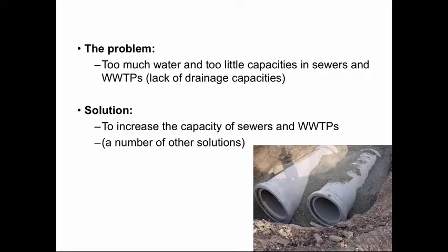So what can we do to solve this? The easiest and simplest thought is, okay, if the sewers are too small, why not build new sewers? But this is not that easy. If you take the Norwegian case, we can't even keep up with the normal rehabilitation needs. The industry here has estimated that we need to renew our wastewater pipes by at least 2% every year. The minimum expected is 1%, but the result is 0.6% per year. So that is just to rehabilitate the existing sewers. So how are we going to finance new sewers?